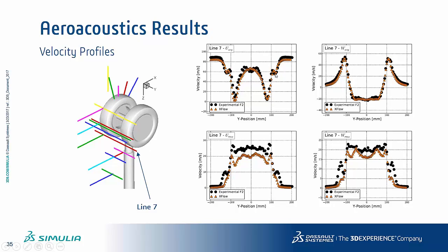And again, drop against separation, stagnation area here. Then again, this velocity recovery. The same for the W component, very well matched. We've got correct profiles of velocity, and in the end we also have the correct fluctuations of velocity as well at the right level.